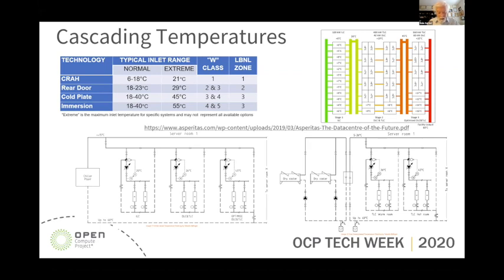I should mention that cold plates and rear doors running at elevated temperatures may not remove all the heat and may require lower temperatures and a secondary removal process, or it might require a reduction in compute performance. So for example, for us, we may have a few very hot and humid days where our temperatures to the rear doors run warm or warmer than desired.